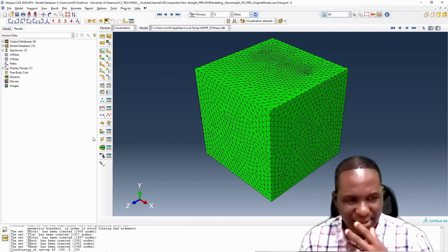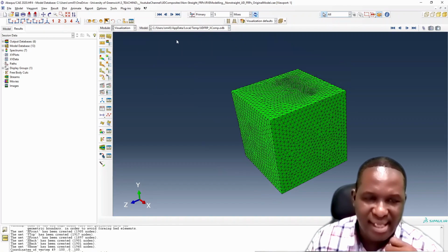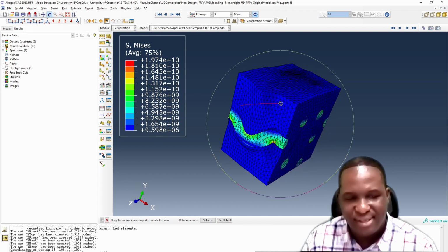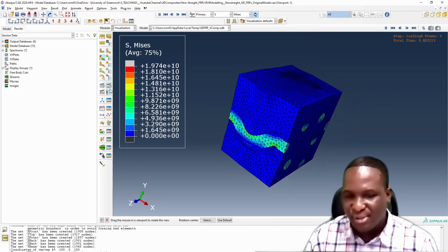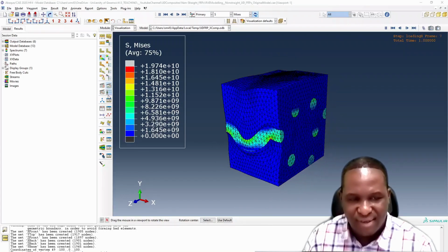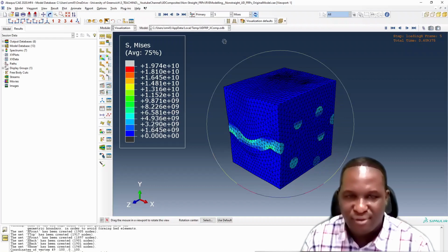Okay, so we've got all the results set up, and we're going to run through them individually. With the X compressive case, this is what we find. If we analyze what's happening, there's this compressive behavior, and like we expected, there was a buckling of the fibers due to the compressive loading. So you end up seeing the buckling of the fibers.